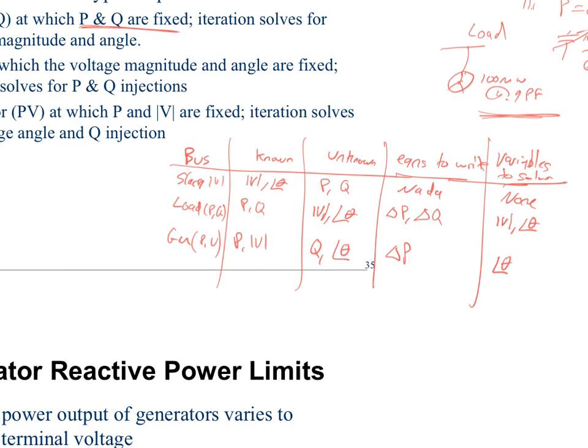And it actually varies because in distribution circuits, there are ones that you can switch on and off depending on the voltage. Many of them are fixed, but there are a few cases when you would have a switch, and it does it in big discrete steps. So it would switch it on, but that's not maintaining voltage. That's just doing like a big clunk, switching over. It's only when you have a StatCom or something real fancy like that when you're maintaining that specific voltage. Generators, though, can switch power factor. They can do that very easily. No big deal. All right, questions?